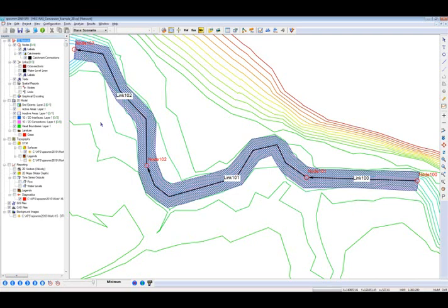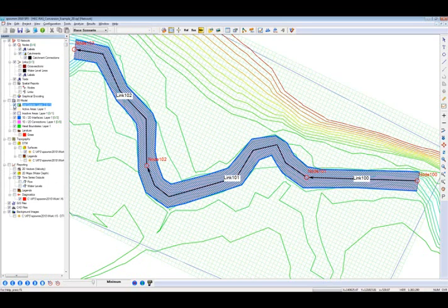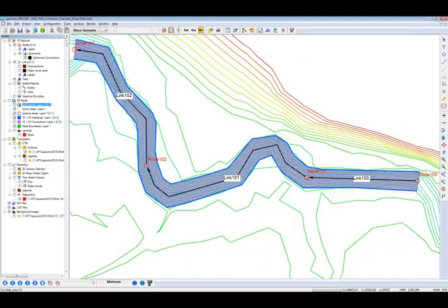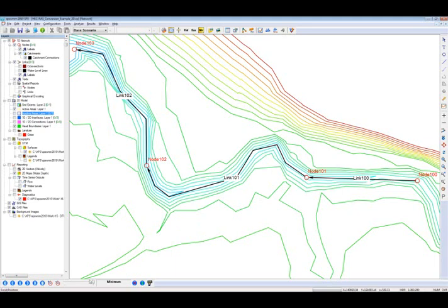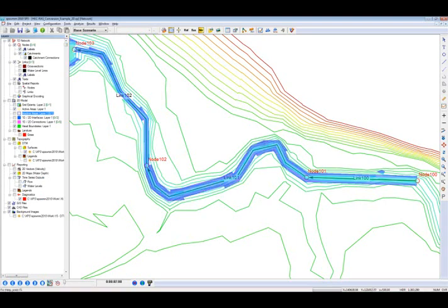Now, from here, we can see that I have added these 1D, 2D interface lines, which I'll turn the grid, and so we can see that those interface lines will transfer flow to those grid cells. And so if I turn this off so we can best see it, the model will begin. We can review the simulation. I have the water depth being shown, and we can play the simulation. We can see the flow enter the model.